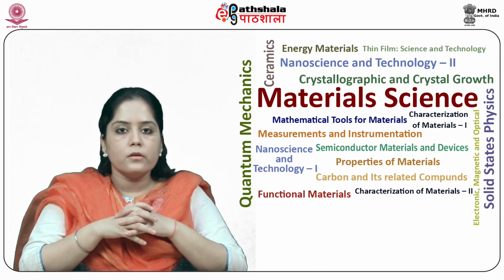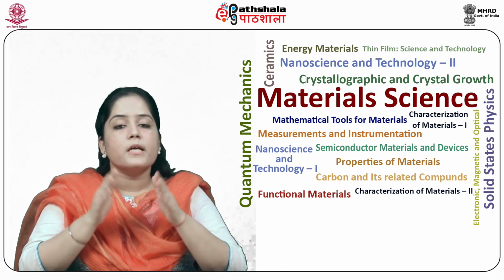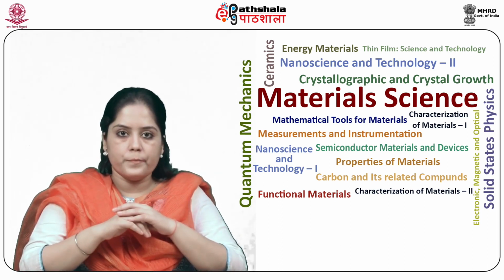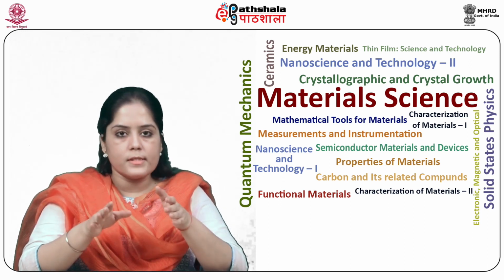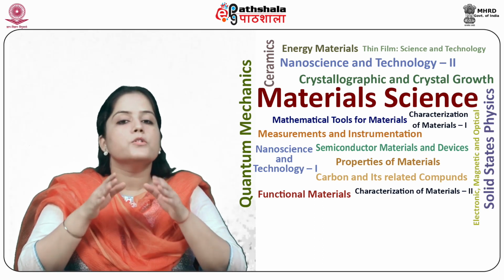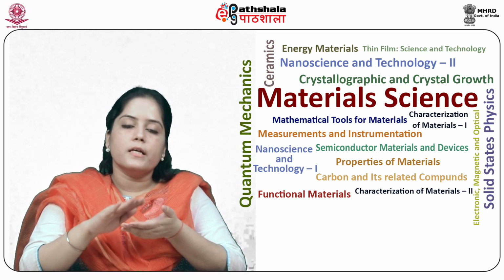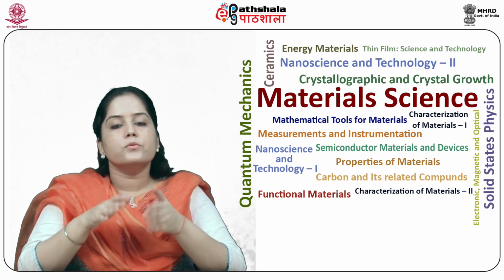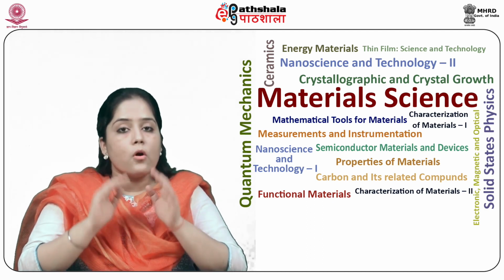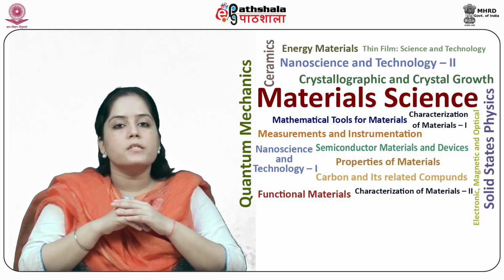Therefore, oxidation of the silicon wafer is the most important process. A three-zone thermal oxidation process is used to grow a thick film of SiO2 over the silicon wafer. The thickness of the SiO2 thin film strongly depends on the oxidation time and temperature.